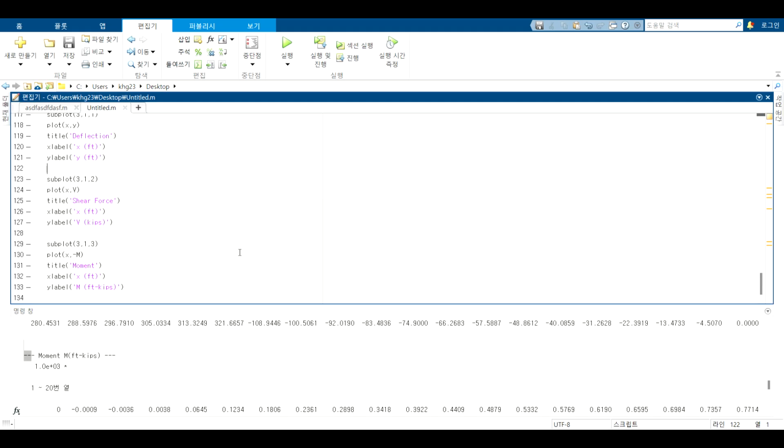The main features of this program are as follows. First, the user can freely configure the number, location, and magnitude of point loads, making the tool flexible for analyzing various design cases. Second, by using the Winkler soil model, the program realistically captures the interaction between the foundation and the supporting soil. Third, by adopting a matrix-based numerical analysis method, the program ensures both computational speed and accuracy while also being easily extensible.